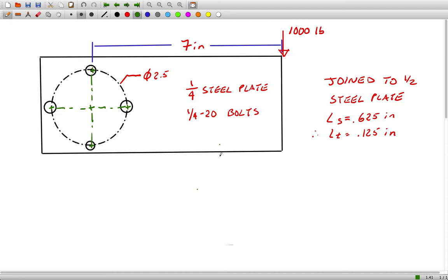You can certainly get bending into a bolt. It's just not very typical of common joints. If you do have bending in a bolt, you can handle it with typical stress calculations with some sort of Mc over I inclusion. But here, the way this is loaded, you're basically twisting this plate about the centroid of the bolt pattern, and as such, there's only torsion applied to these 4 bolts. I'm just going to label them so I know which is which as I start the calculations.